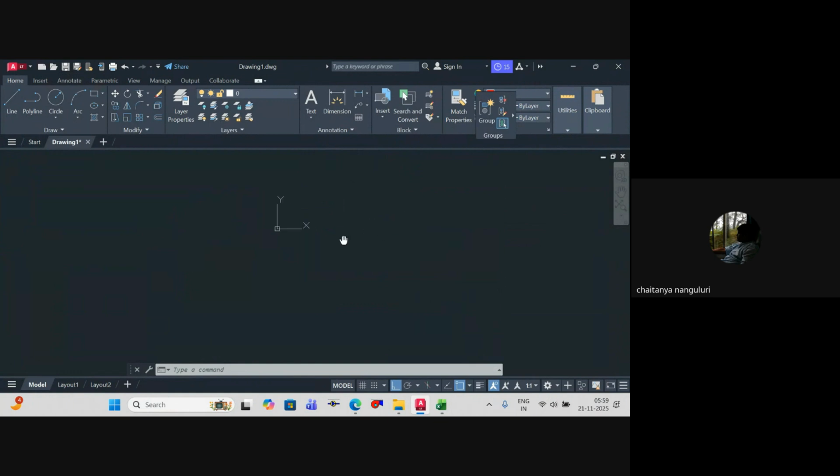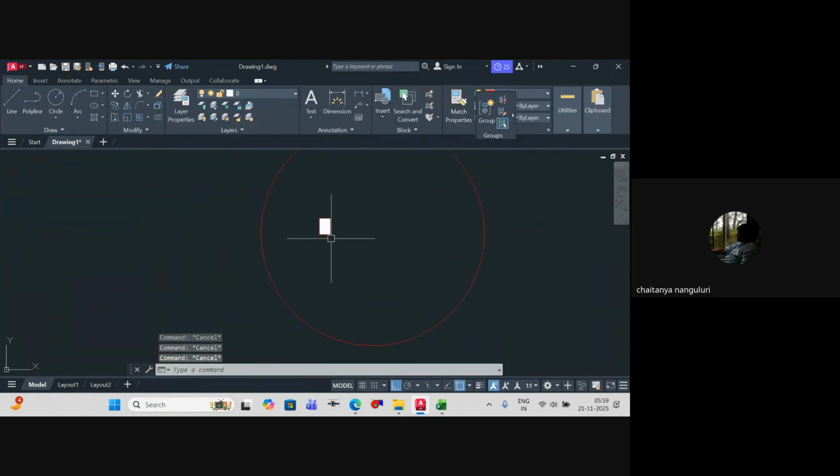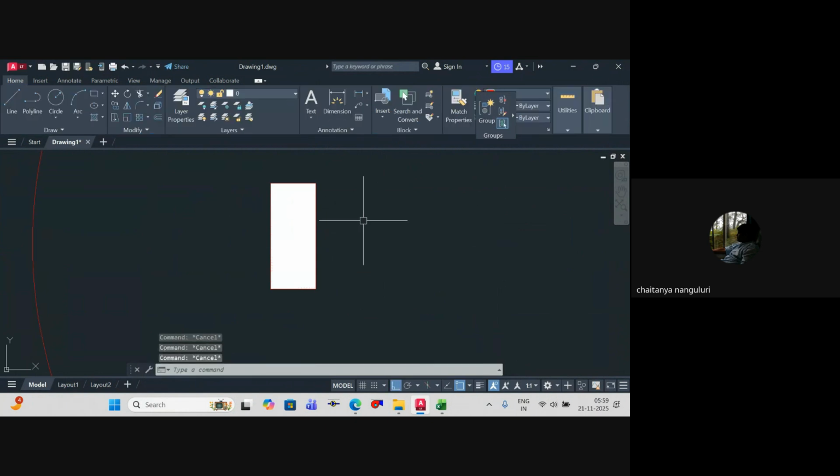So how the ionization type works is simple. You have again a transmitter. Actually, you will not have a transmitter. In fact, you have an ionization material, which will continuously give alpha radiation. Very minor radioactive elements. So it's quite dangerous. When you buy these particular ones, you should even have a clause for sending them back to the manufacturer. You can't just scrap it on the road because it's quite dangerous. Understood? You have very slight radiation.